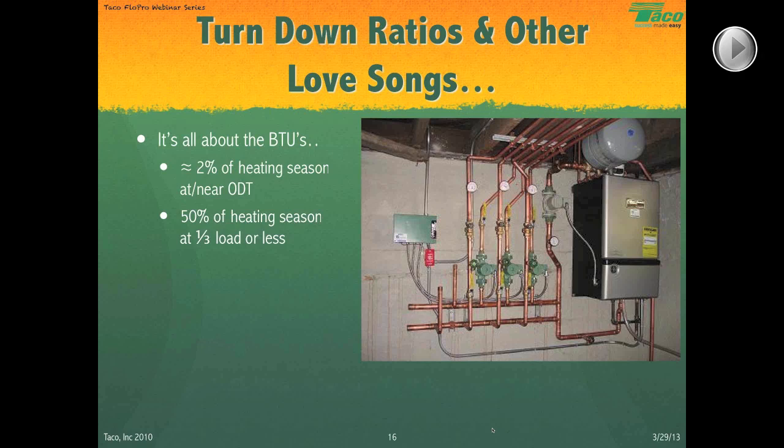Now, it may get really cold where you are, but when you pick that outdoor design temperature, whether it's the ASHRAE temperature or the quote-unquote local custom, you're pretty certain that over the last 50, 60 years or so, somebody's kept track of this, and they've found that roughly 2% of the heating season, no matter where you're at, is at or near those outdoor design temperature conditions. Do you blow past it every once in a while? Oh, heck yes. Absolutely. Are there winters where you don't get anywhere near it? Well, yeah. Last year, the winter that never was, except up in Alaska.